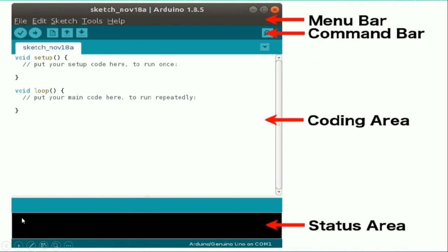You need to read and understand where the error is coming from. And then we have another indicator. This is also very important. If your Arduino board is properly configured, it will appear on the lower right part: Arduino/Genuino Uno on COM1. It also indicates that it is connected to the COM1 port.